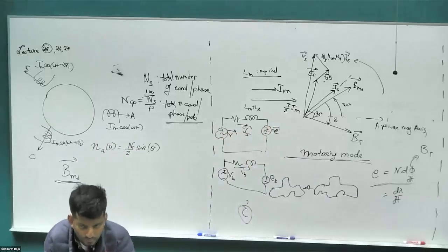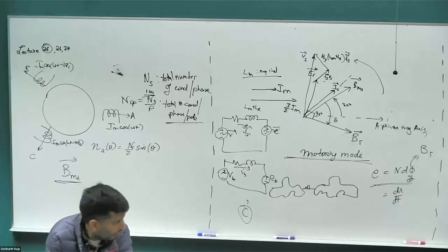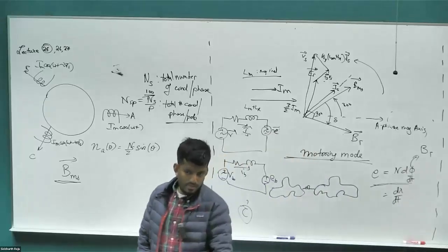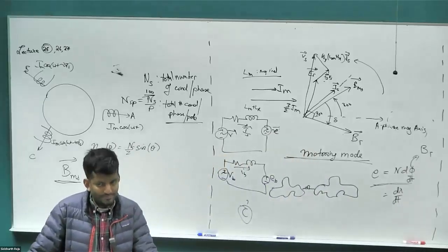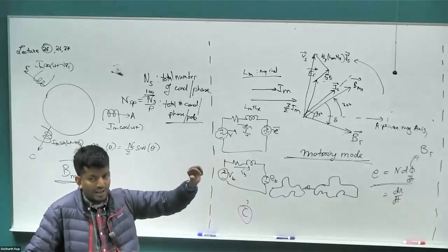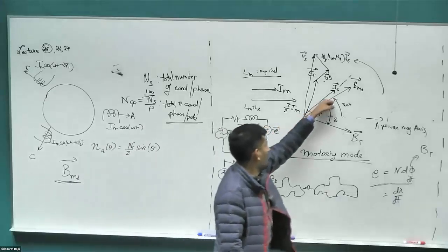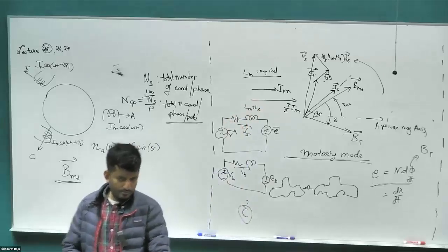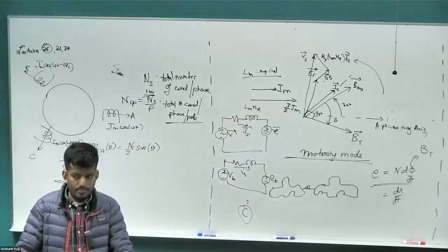Just like if you were to write down a space vector, like on the homework, it says write the space vector. How do you label the angle? Do you use the same notation as a phasor, or is it different? Which angle? So you would use this e power j omega. Okay, so the angle is a function of time, basically. Yeah. So it will be e power j times brackets omega t minus whatever the angle equivalent is. So in this case, if you're drawing this, it will be e power j omega t minus pi by 3, pi by 6. Right? So, any other questions? Okay.